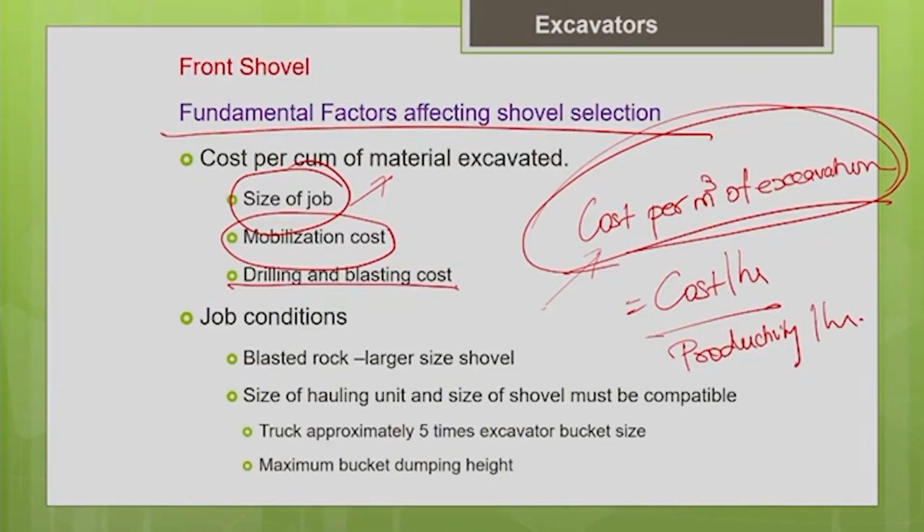And another important thing you have to note is that when you go for a bigger size shovel, so you know that very commonly we use the shovel in a quarry, for quarry work. When I go for a bigger shovel, the bucket will be able to handle bigger pieces of rocks. So accordingly, I can change my drilling and blasting pattern. I can have an economical drilling and blasting pattern in such a way that the rock pieces can be bigger.